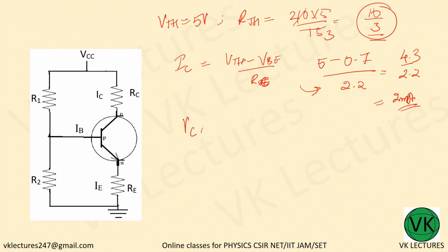Now what is VCE? VCE equal to VCC minus IC into RC plus RE. What is VCC? 15 volt.